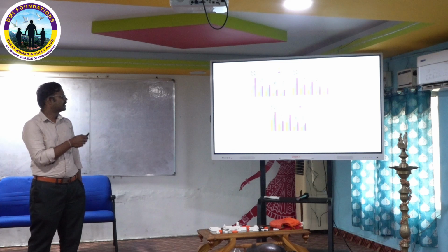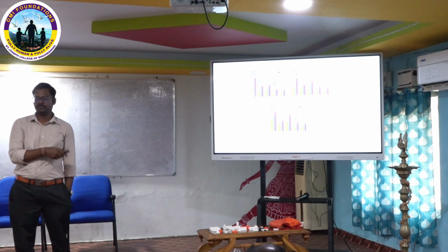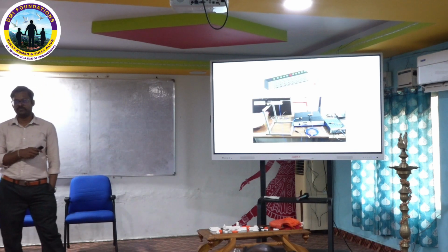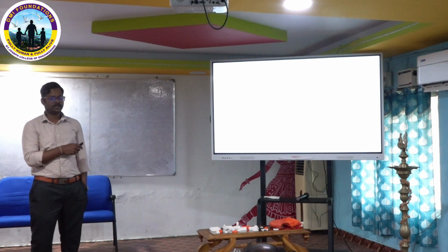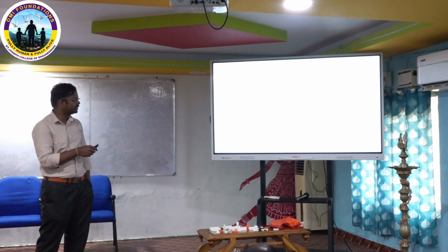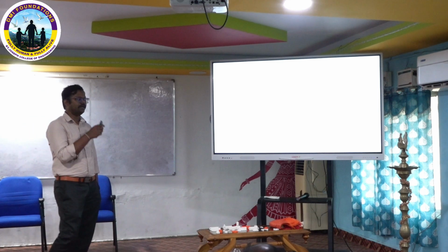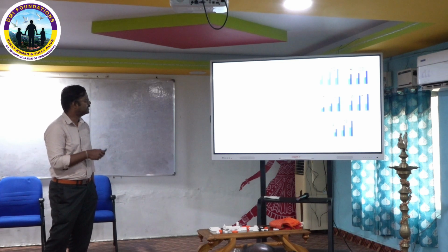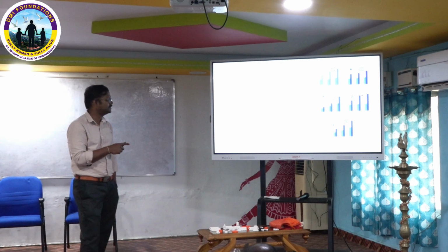Then this is a comparison. All the structures show that compared to 10 and 20%, 30% gets more energy absorption. Then I also did vibration damping testing for the same structures, and I formulated the FRF, that is the frequency response function. In that I calculated the frequency value and damping ratio value. This is the frequency response.